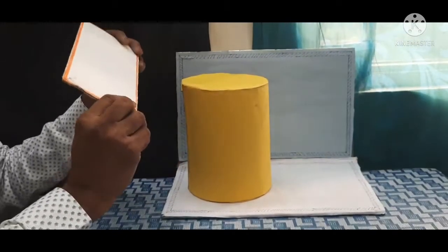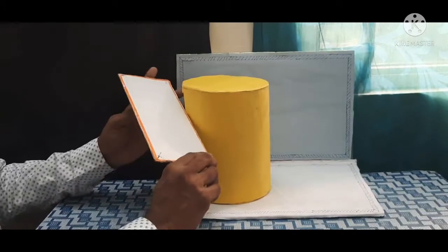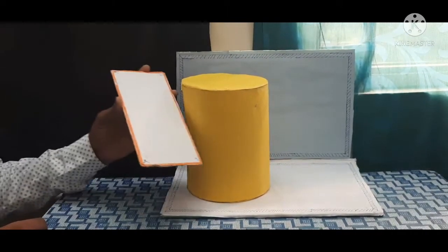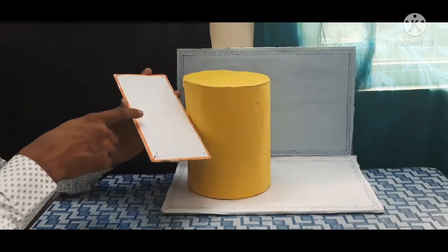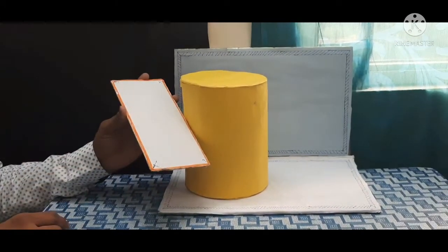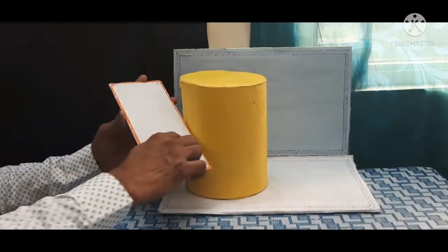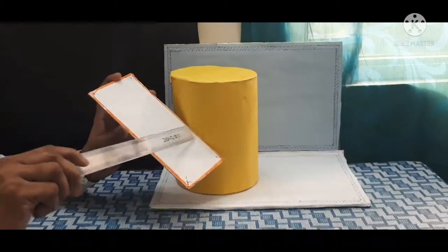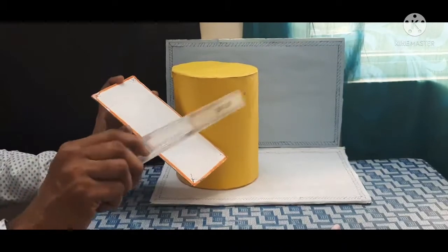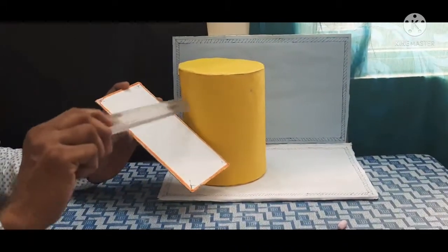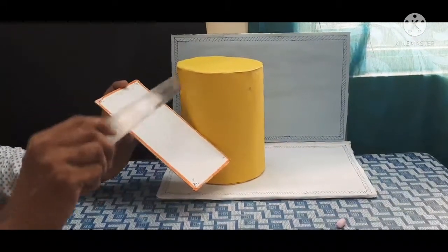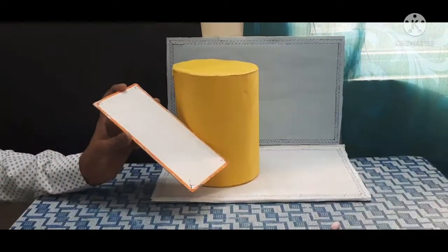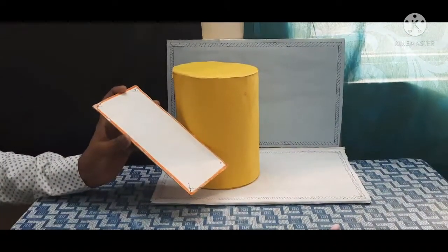We have this cutting plane, and we cut this solid by keeping the cutting plane 35 degrees inclined to HP and remove the top portion. At that time the cutting points are marked on the top surface. Then the corresponding true shape and sectional top view we are going to draw in this problem.